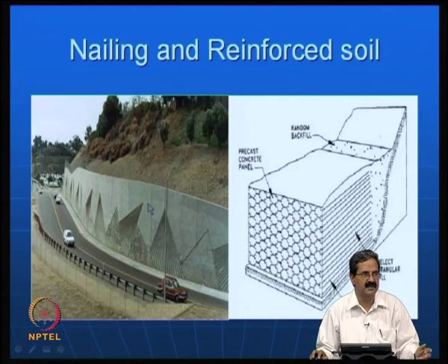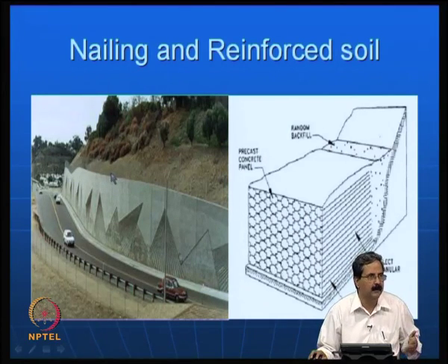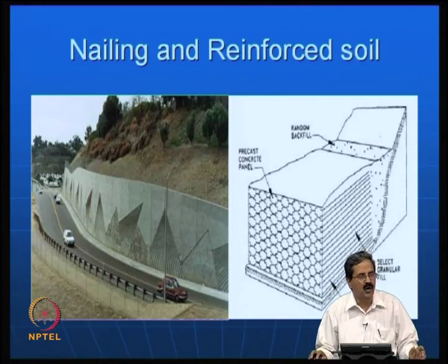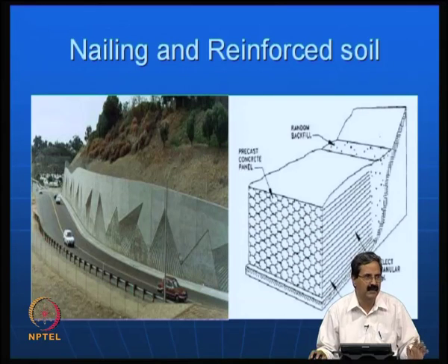In fact, our own underpass construction at AASC, which you see in Coffee Board, is an example of this technique, where we did not disturb any of the trees at the top. This is a very classical example of how you use native soil and make it stronger. There is no point in disturbing the soil and then replacing it. Whatever the existing soil is, try to understand the soil behavior properly and find out the soil properties properly. If it is not strong enough and has a tendency to collapse, calculate how much reinforcement is required to make it stable, that is all.